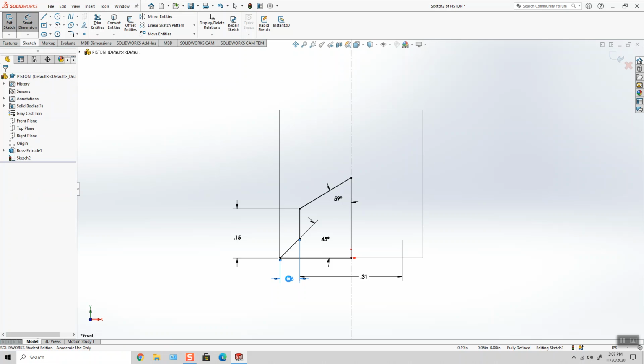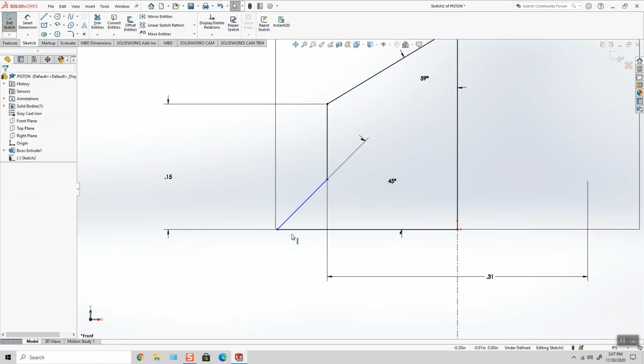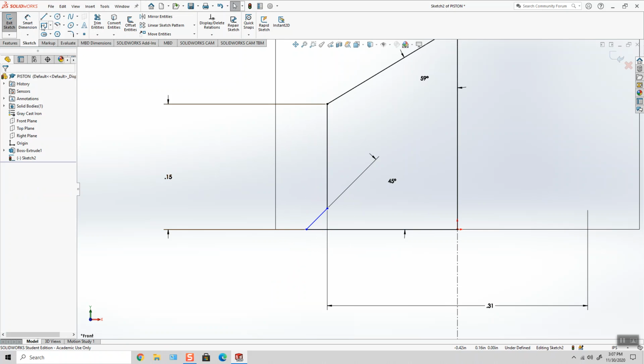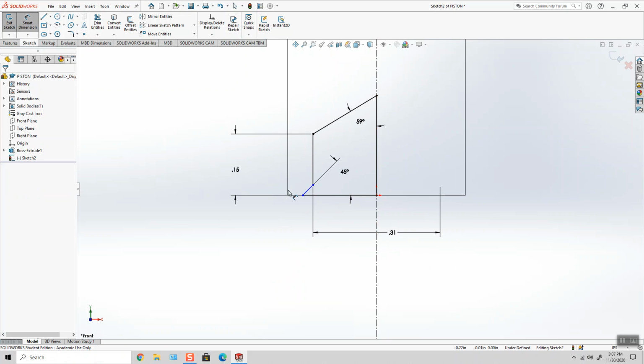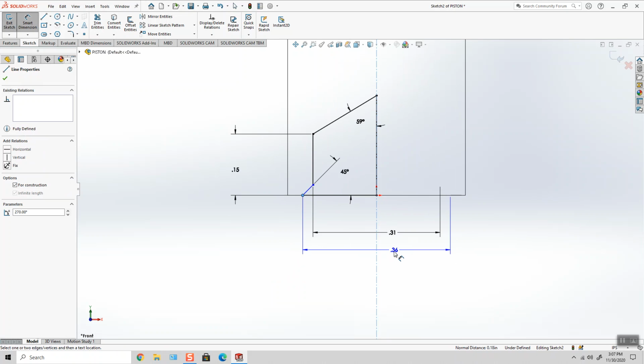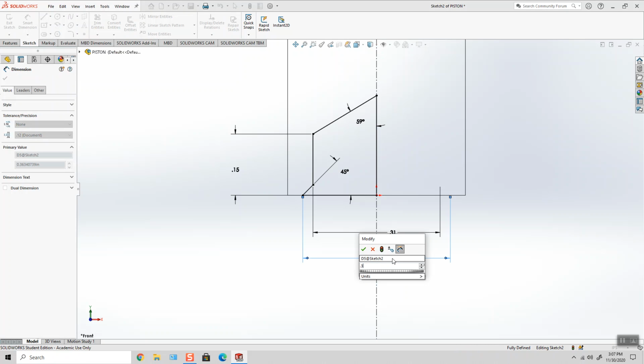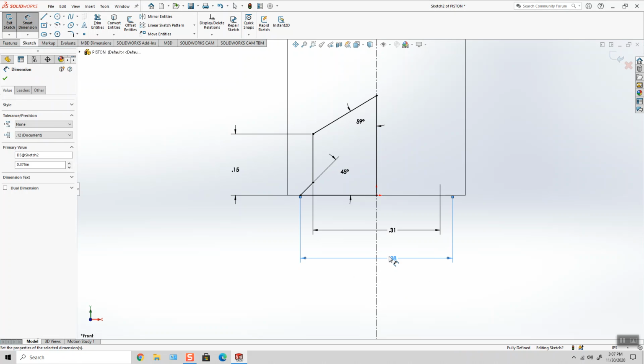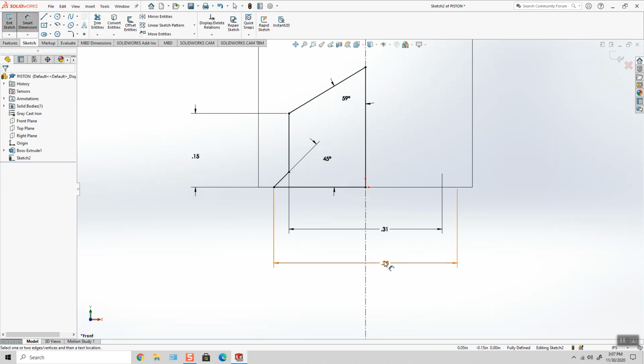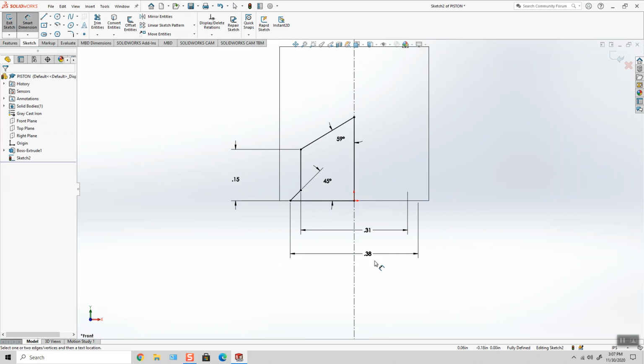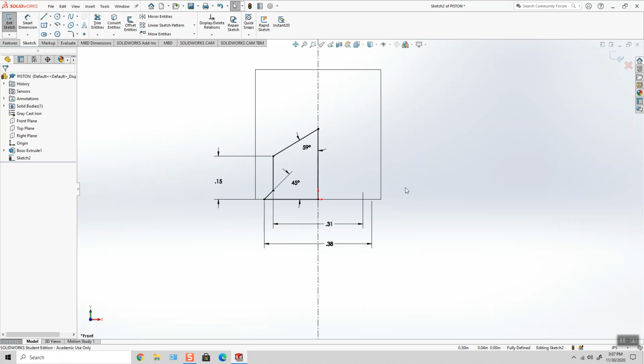Or I could control the size of the countersink by giving it a diameter. So if I knew what types of tooling I had, and I said, oh, I have a 3/8 bit, and then I plunged it into the part, now I have a 3/8 countersink. So if it's not specified on the print, typically that chamfer isn't super important.